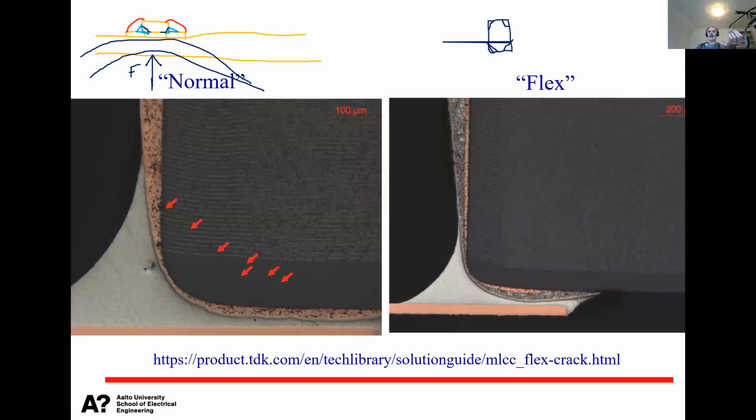It is not mechanically fracturing, because you can see that, for example, this solder joint here, there's no defect here. So mechanically, this component is perfect. Electrically, it might be quite close to okay, but still there's some problem with the actual capacitance value.